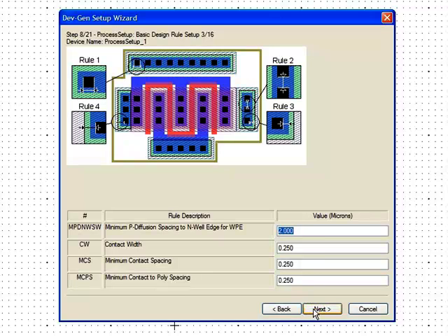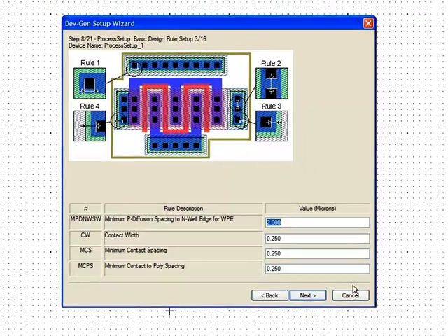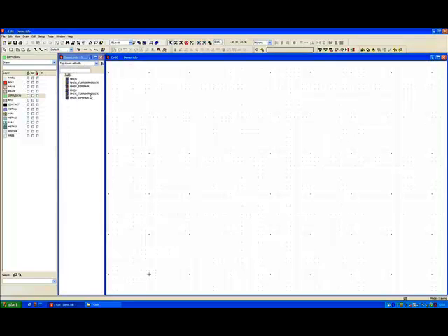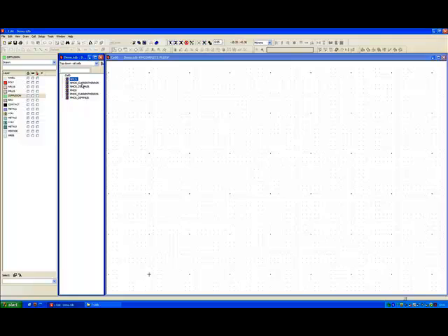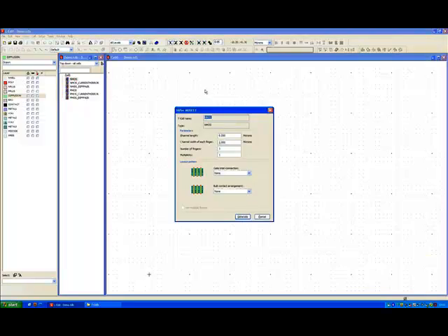Obviously, the number of design rules will scale depending on the number of metal layers and the technology you're on, but the process here is a one-off setup process that takes 15 to 20 minutes. But it's very, very quick to do. More importantly, you can go back at any stage and change the numbers, and once it's done, what you'll end up with is a parameterized cell that straight away on the technology you want to use is going to be DRC and LVS clean.